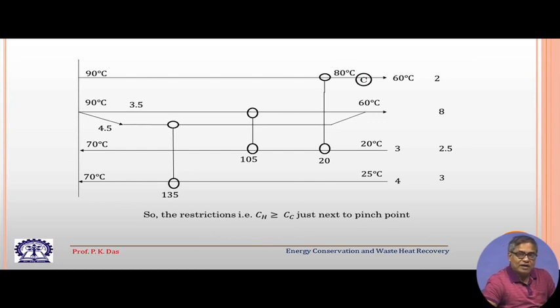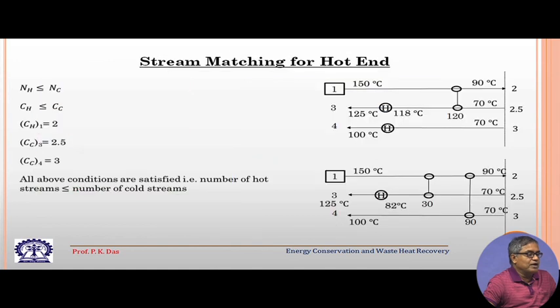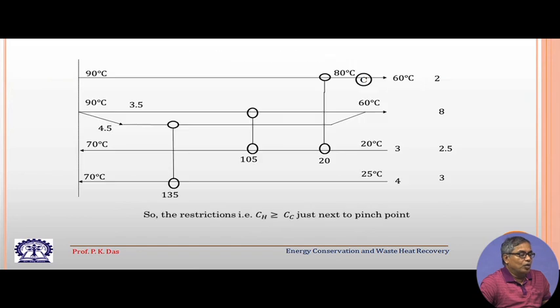Other possibilities are there, we can have an alternative design of the cold end. So, we have got some alternative designs of the hot end. If you see that we have got two alternative designs of the hot end, and we have got one design of the cold end. Of course, we can get alternative designs also, and then we have got several alternatives, and then we can stitch. One possible hot end design can be stitched with one possible cold end design. So, then it will give the total design of the heat exchanger network, and our heat exchanger network synthesis is done.